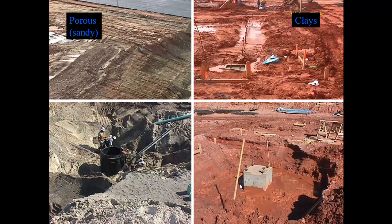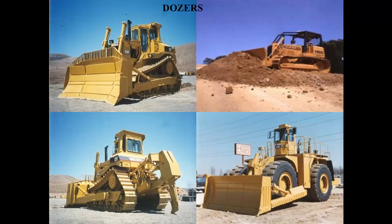When we talk about cohesive soils, those are soils with a little bit of moisture. If you can take a little bit of that material and squeeze it in your hand, and when you open your hand up it maintains its shape, that's what we would refer to as a cohesive soil. Whereas sand, if you do the same thing and it's dry, even if it's a little moist, you squeeze it in your hand, when you open it up, the sand will kind of fall apart. Those are the differences.